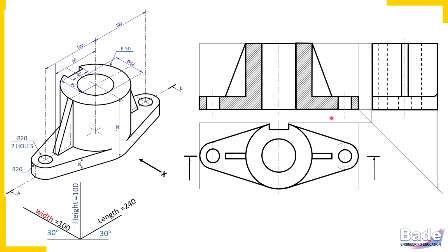On your screen, watch this sectional view. Nowhere there is hidden line. If largest surface of a plate appears in sectional view, then don't show hatching lines on the largest surface of the plate. Such plates are to be assumed uncut.